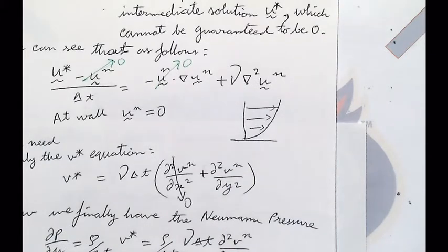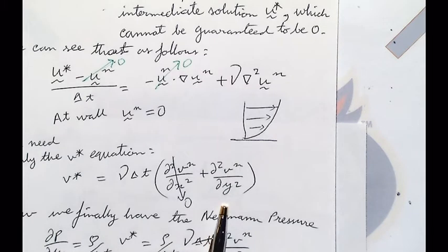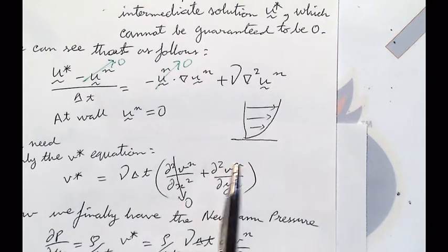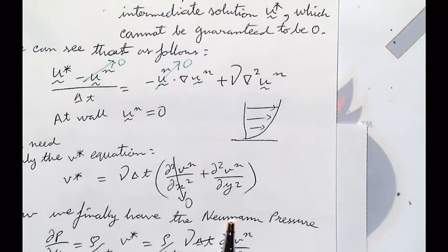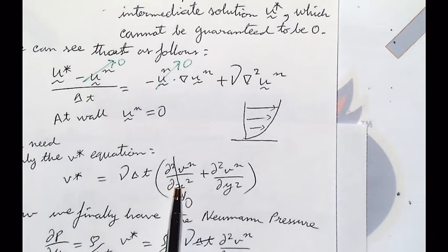But you say it's not 0, why? That's a U over Y, right? This is V over Y also. This is d2v dx squared, d2v dy squared. For example, the first one, because we consider a developed flow, X is not changing. Yeah, that is a very good assumption. But the Y is changing, in the boundary layer, yeah, it's changing.